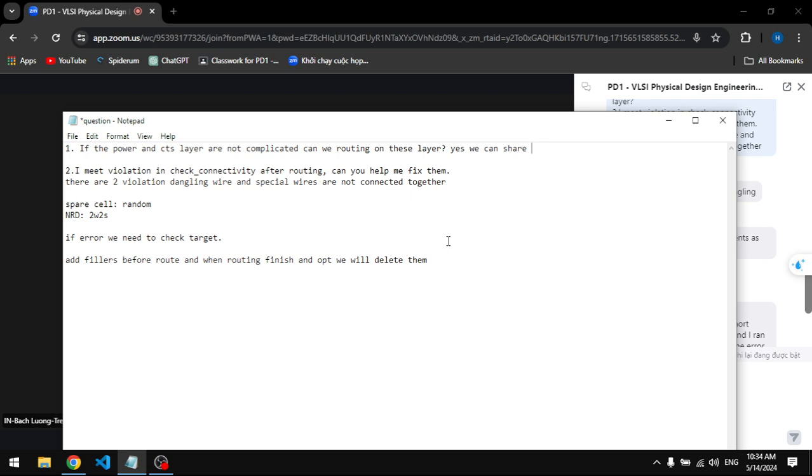I don't recall we had any dangling wire in the run that I did. Sometimes at the via connection intersection, if one of the steps is too long, it will complain that one path segment will be dangling. So we have to bring that up and look at it case by case. To simplify, we can ignore the dangling errors, but the shorts have to be fixed.